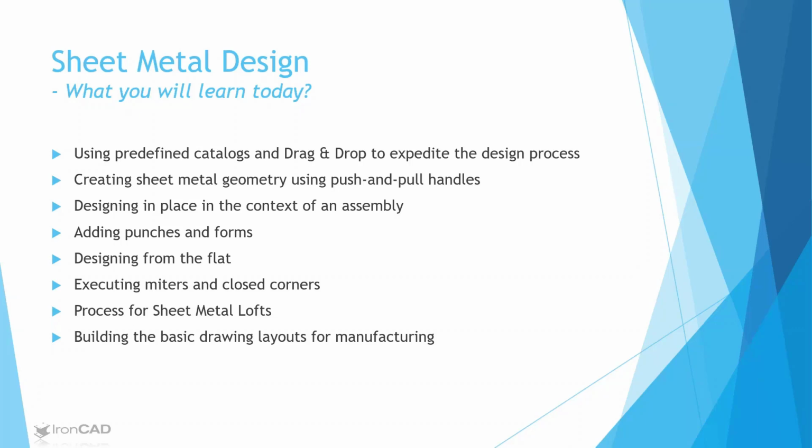We'll also show you how to design from the flat. For example, if you have a 2D DXF that may be coming from a supplier or another customer, you can bring it into IronCAD and build up a sheet metal design part from that 2D DXF. We'll also show some of the more advanced capabilities for miters and closed corners on the sheet metal and how they're fully associative.